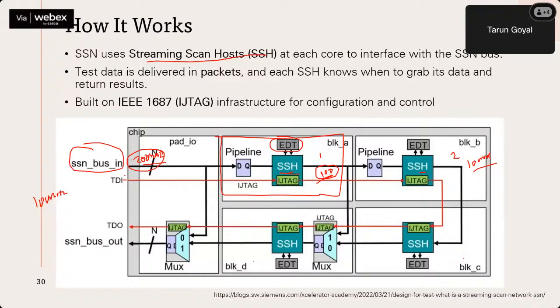So okay, I have n number of channels. Suppose n/2 was required by this EDT and n/2 was required by this EDT. Now data was earlier coming at n multiplied by 100, right? And this was consumed. Now also this much data is coming, but it's coming at the rate of 200. So the same n number of patterns are coming at the rate of 200 megahertz.